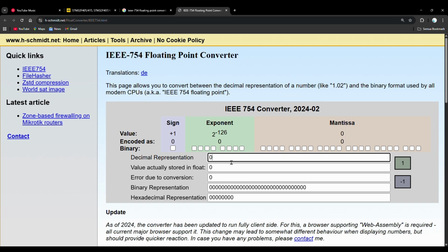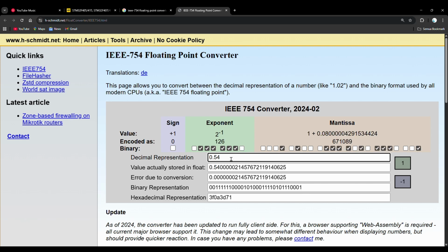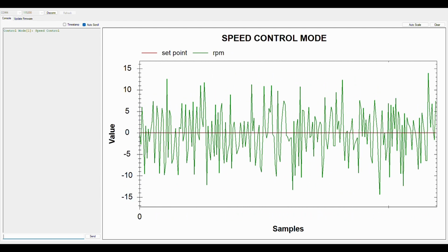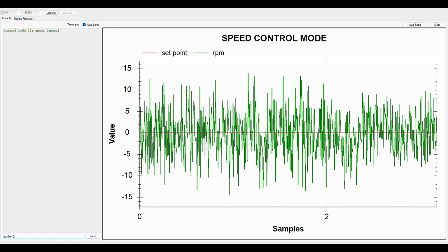The concept is to transmit data in 4 bytes binary format according to the IEEE 754 float standard. With this approach, each value only requires 4 bytes. This makes the data transmission process much faster and more efficient, while the displayed values retain exactly the same precision as those in a microcontroller. In this software, the plot's title and legends can also be modified by sending specific protocols.